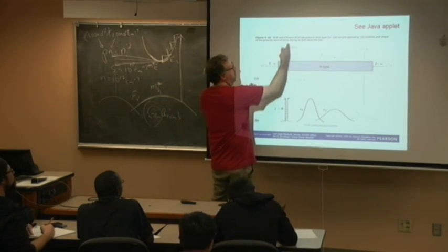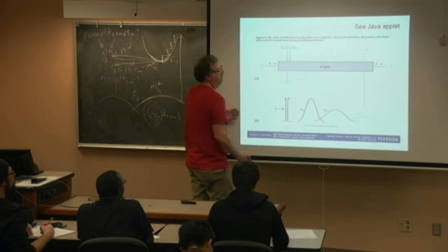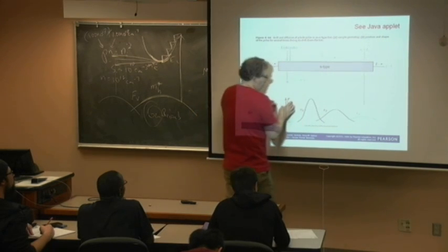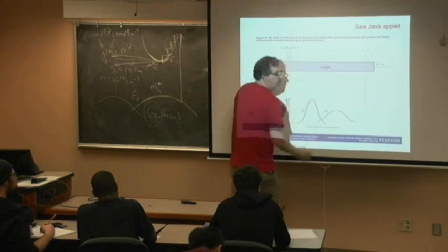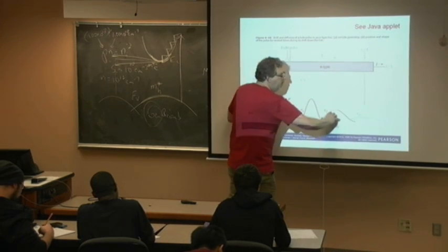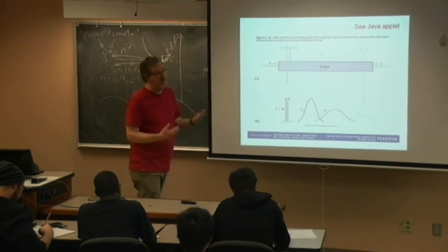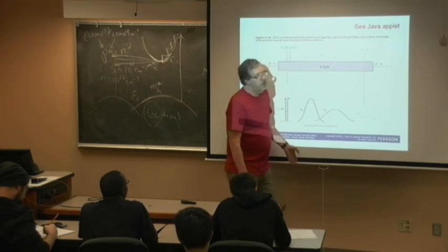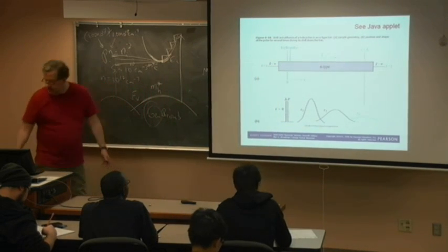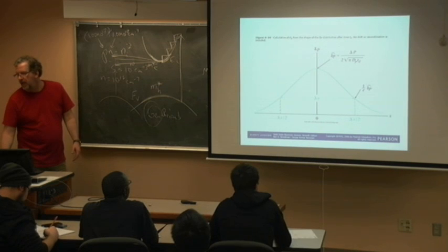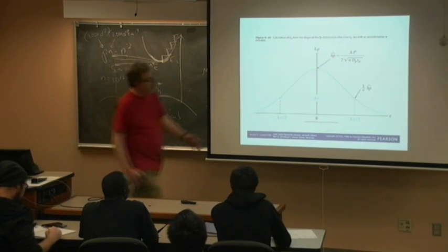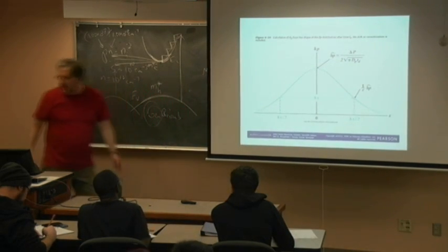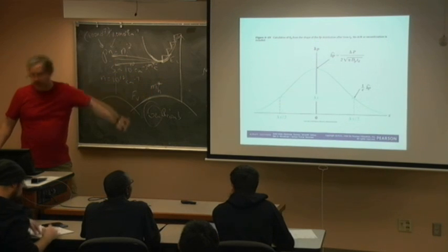So you basically send in this light pulse, this delta function of electron hole pairs, and if you apply a voltage, the ensemble is going to move down by drift, and diffusion is going to cause it to broaden out, but they're really manifestations of the same thing through the Einstein relation, and so it's another way to measure mobility and diffusivity. You can tell by how much it broadened by a given time. You can actually calculate the diffusion coefficient. Because you can see that pulse on an oscilloscope, essentially.